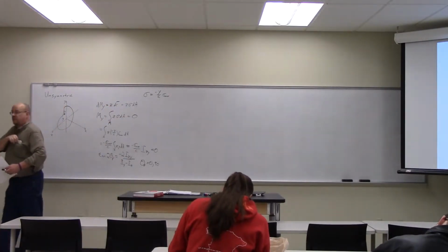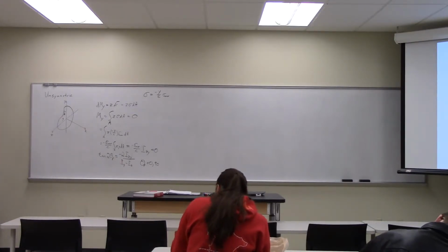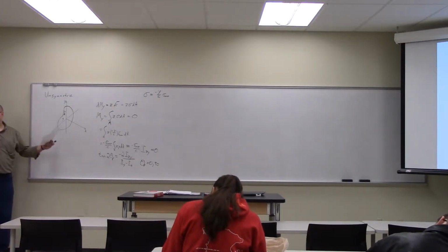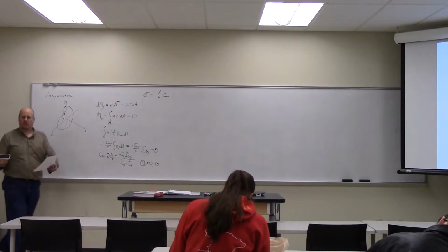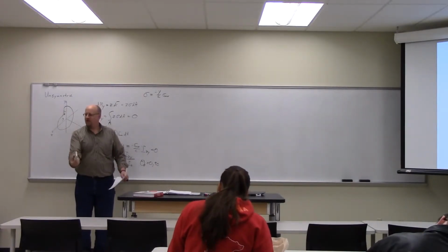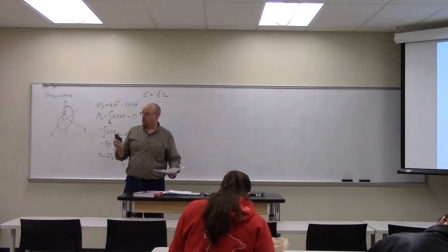And this is again why, if I'm at the major or minor axes, I can get this thing to flip fine. Because my moment is not inducing a bend, or in this case, a dynamic rotation, in any other direction. I'm getting pure rotation here, and I'm getting pure rotation there. Because those are the major and minor moments of inertia, the maximum and minimum moments of inertia.